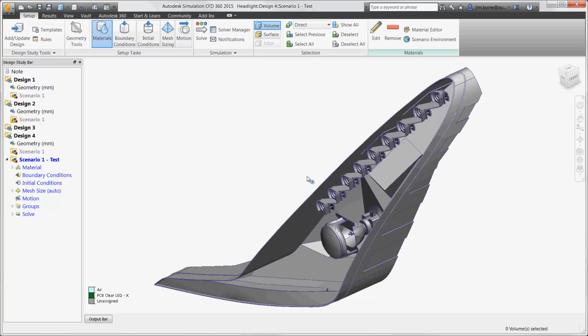Combination lights such as these create new challenges for OEMs and exterior automotive lighting suppliers. Our goal in this design is to preserve the clarity, brilliance, and life of the LEDs. In order to do this, we have to keep the LEDs within operating temperature and also minimize the temperature difference between each of them to avoid color shifting.